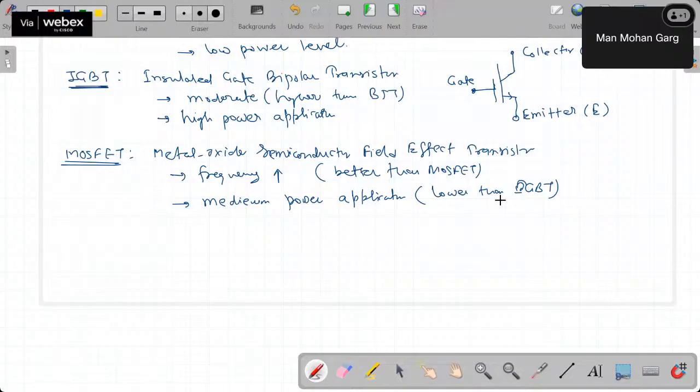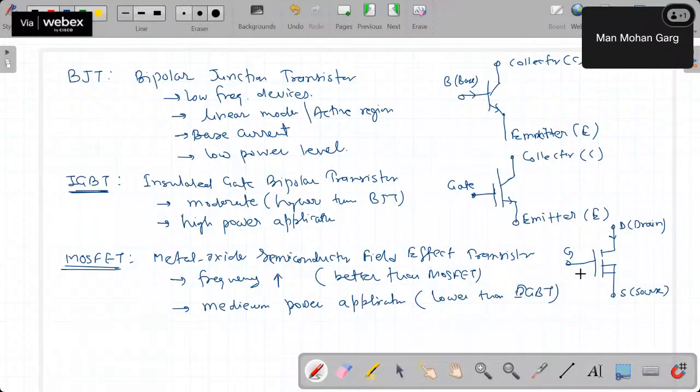By controlling the gate to source voltage, we can control the on and off time of this device, and then the further impact on the circuit function. So that is the way we can use these MOSFETs. Normally MOSFETs are silicon based. So far they were being used, but nowadays wide band gap, WBG, devices are being used. You must have heard of silicon carbide and gallium nitride devices. These devices can withstand large voltage, and they have large temperature handling capability. One speaker will talk about these in more detail. So these devices are growing in popularity.